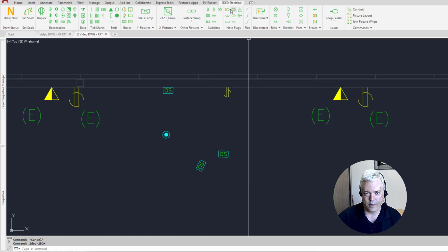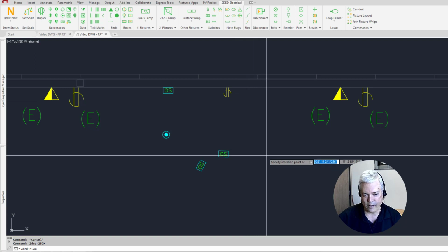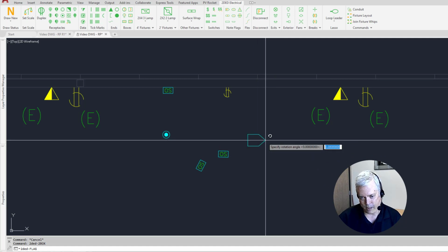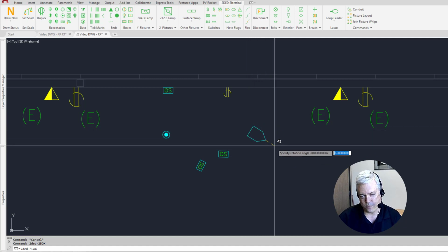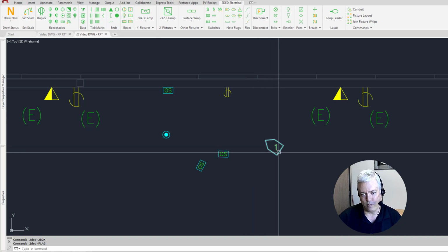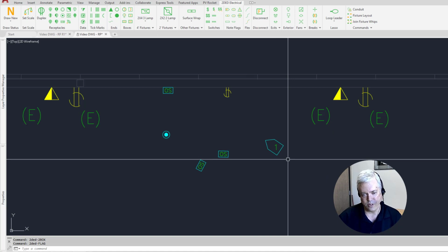There's also this, for instance, here's a flag that floats in that's meant to be on paper space, so it floats in very small, but once I pick, it goes to model space scale, and if I give it a rotation, that variable rotated, and it was forced to 0. And so there's an example of everything working together. Layers are controlled, blocks are controlled, and there's an options box that sets all of these variable flags so that you can get the behavior that you want.